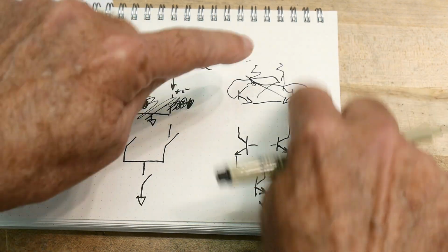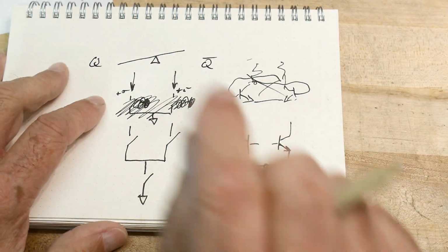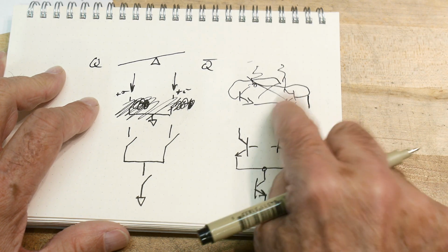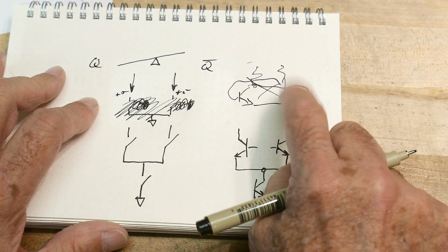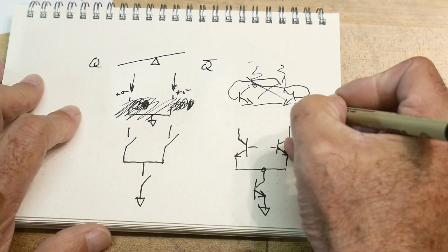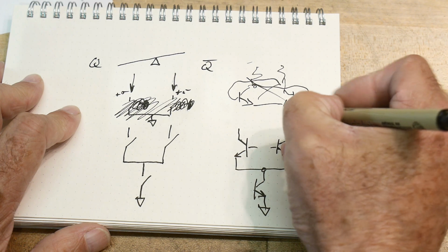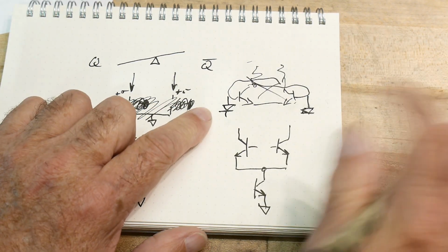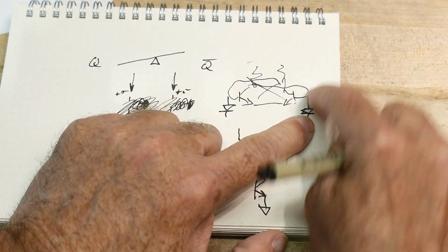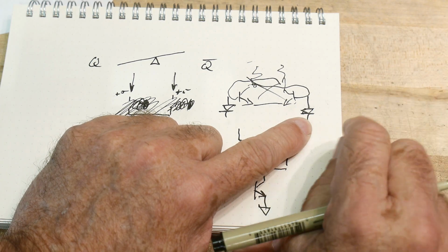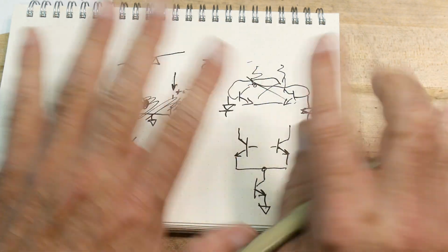And so this is a teeter-totter, right? And you can kind of reach in and you can pull down on one of these. So if this one's already pulling it down, fine. But if this one's not pulling it down, you can reach in here and you can pull it down. You can do that with diode switching. You can put in some diodes here, okay? And that diode switching, if you go over here and you ground here, you'll pull that side down. And then the diode will get out of its own way. Once you let up on it, it'll get out of its own way.